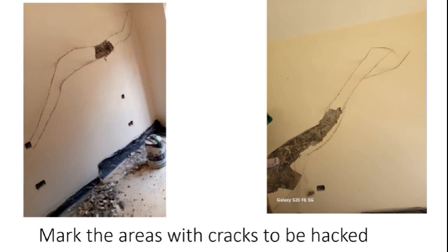And interrogate also the quality of your infill. And to do that, mark the areas with cracks, so that after a while, maybe even after a whole year, you can observe whether they are growing, and also allow them to settle fully, to consolidate fully, to look outside and make sure that there is no water coming to undermine your foundation and cause issues.